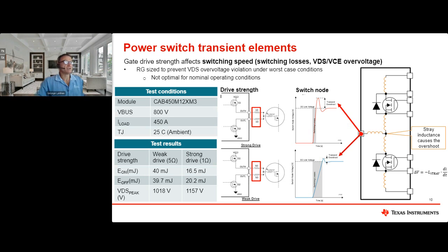And what you see here is, again, in engineering, everything is a trade-off, right? So what you see here is the slew rate, because it's essentially a slew rate control driver. So the slew rate is fast, so the slope is much sharper, at the expense of a higher transient overshoot. And so if you switch to the weak gate drive, depending on the operating conditions, and you will see here in the rectangle, now we're using, of course, higher value resistors, 5 ohms externally, then now you see that the slew rate is slower, so less sharp, but now the overshoot is much smaller.